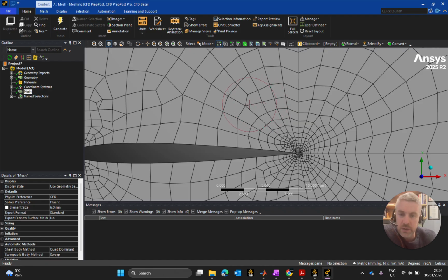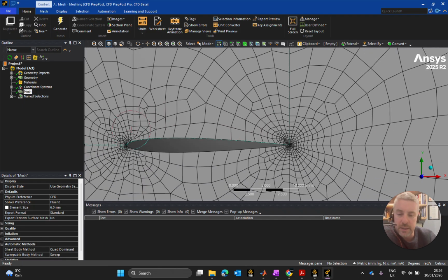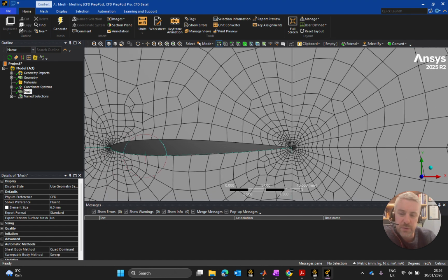However, in a structured mesh, what you can do is tune it in specific areas. But as I said, it takes a good bit more assessment to be able to grid the structured mesh and to do it well. The unstructured mesh will work, but on an external flow problem, especially one with Reynolds numbers in the region of what we're dealing with, between maybe 25,000 and 55,000, the effects along the wall here are fairly substantial.